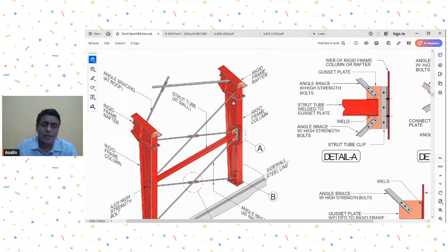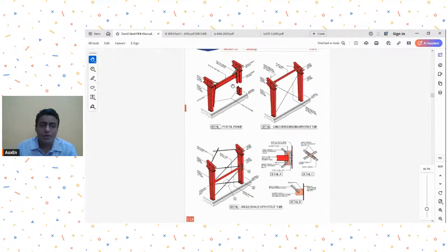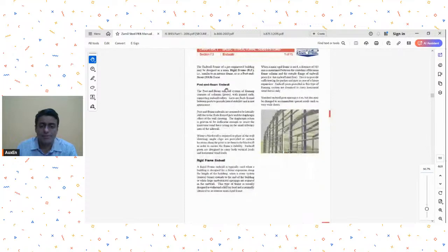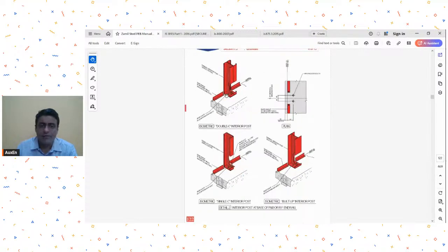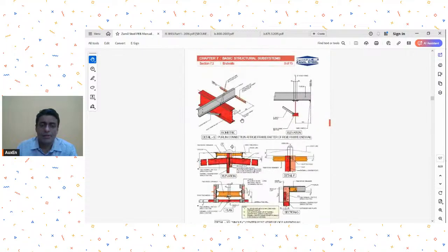They will put it slightly below so as to keep the column rafter section free from any other secondary connections. So you can come up with these connectivity solutions. So there is no one right answer for this. You have to come up with these systems, or you follow the systems that people have standardized. Okay.